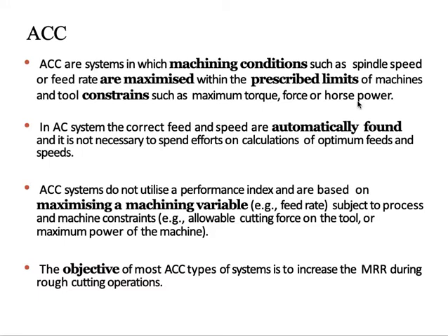The constraint violation detection logic determines whether a process variable has exceeded the predefined limit or not. If a constraint violation has occurred, the ACU logic subsystem increments or decrements the value of the ACU output such that the process variable is within the predefined limit.